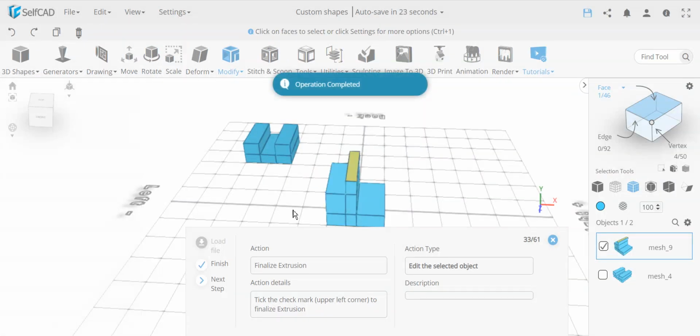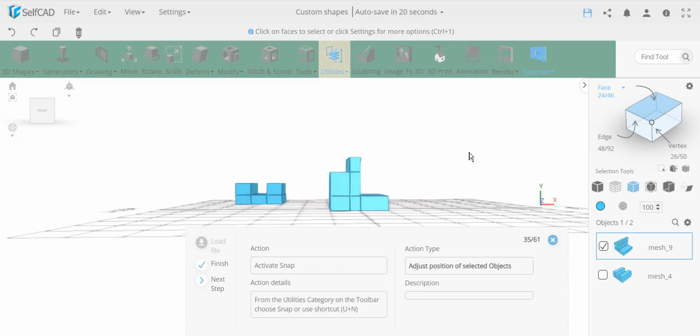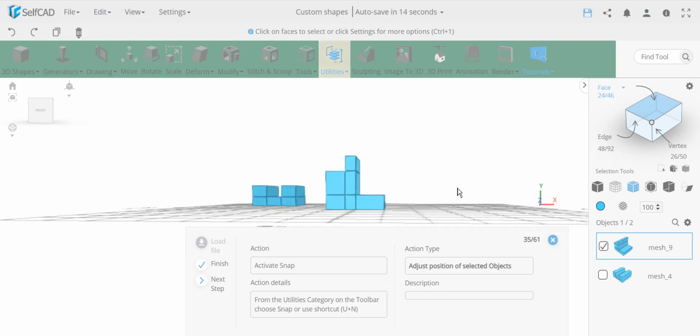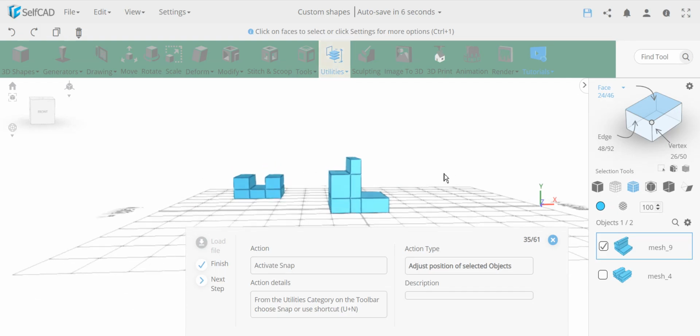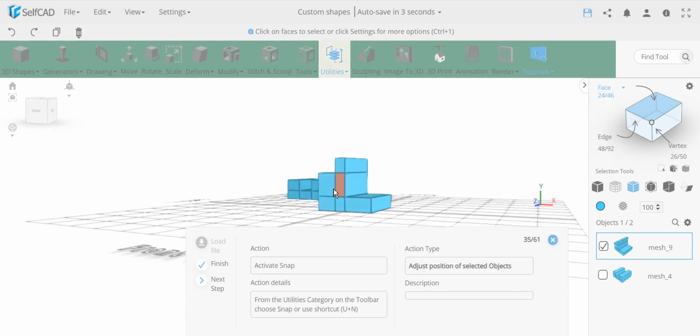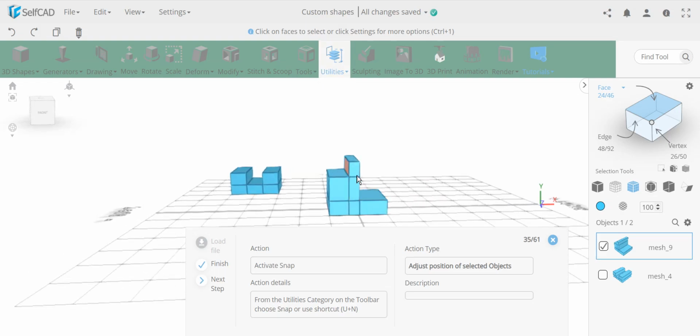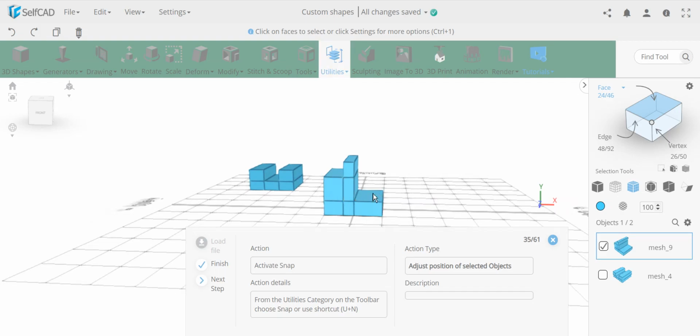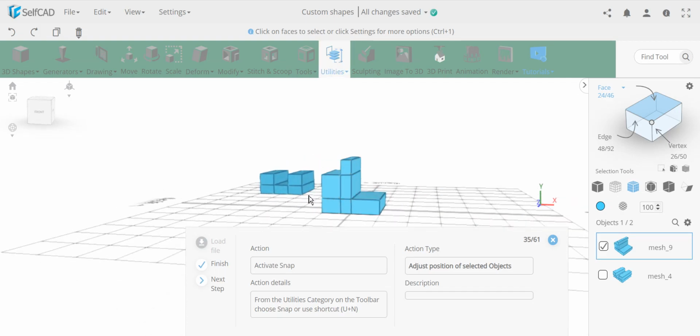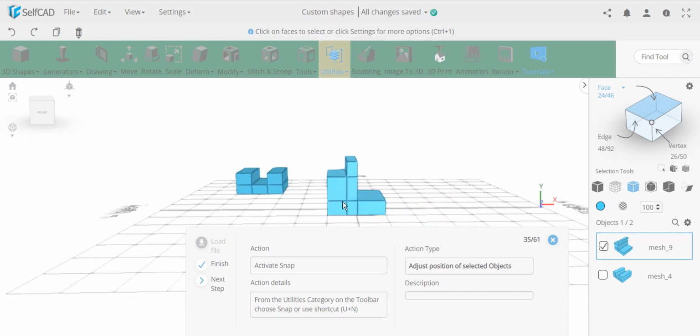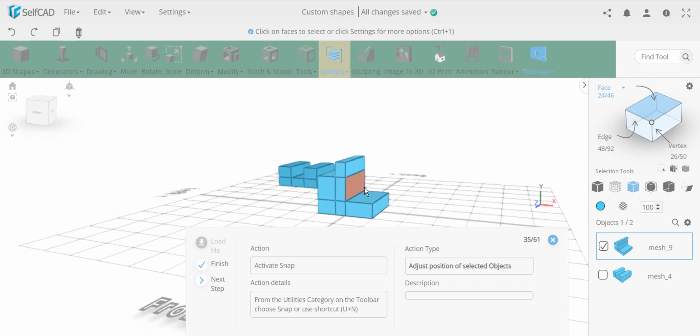But the main idea here is that this could have been done in one shot. First extrude that, and then this, by the amount this is, I think it was 40, and then make this 40 or whatever, I forgot to pay attention how much this was, but make this entire thing one shot extruded. And the reason it was not done that way is because then we wouldn't have these nice quads, these nice loops. If you make this in one shot, this would be flat, you wouldn't have this line, it would be some triangles connecting them. So this is a good way of learning how to build stuff and keep nice loops, which is easy for loop selection, but also a much nicer topology structure to work on later.